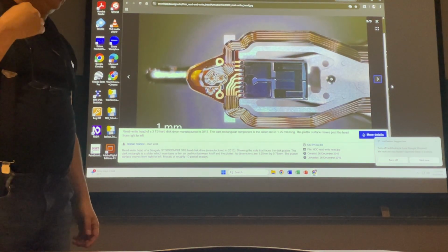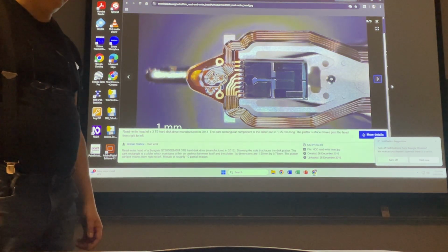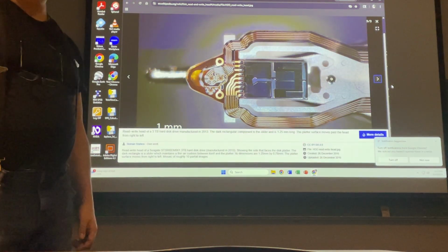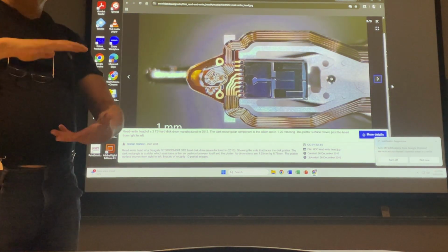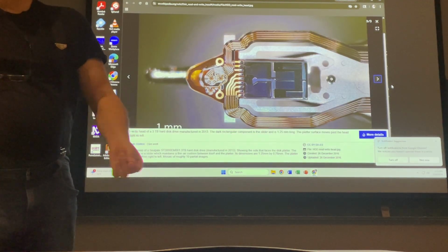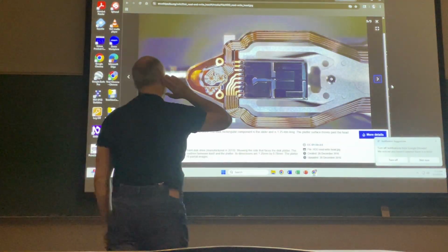But as the drives get older, they get sticky. It's called stiction. Then suddenly you turn on a drive and you hear a ticka ticka ticka as it's trying to unstick itself. You can smack it with a hammer, don't smack it too hard, and it will let go of the surface, and then it'll be okay. That's a good warning to get another drive fast, because you're going to lose it. You have to know how to hear it first. You can hear it if you're good.